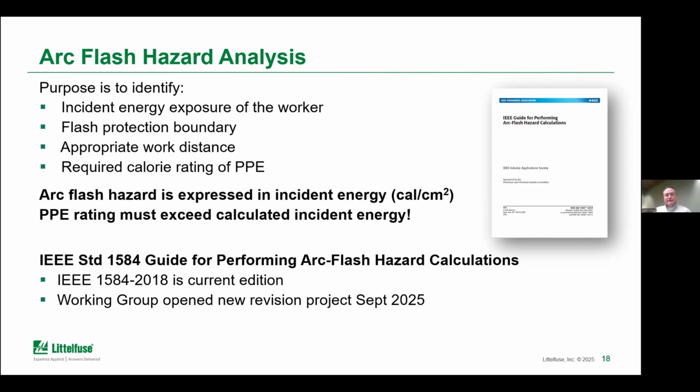There are a few different standards out there, but really what I find to be typically the most common guide or standard for actually doing the calculation is IEEE 1584. 2018 is the current edition. It's based on many real arc tests, and then taking that data and synthesizing it down into a formula that you can calculate what is the anticipated incident energy, based on all the parameters of the system.